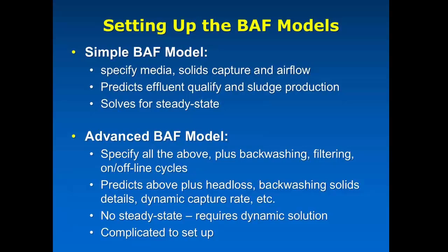It is quite complicated to set up. I'll be frankly honest, it's actually the most complicated thing that we have in GPS-X, is the advanced BAF model. And I had worked on a couple of projects recently where I didn't need all of that detail. I just wanted to get the right amount of surface area with the right amount of aeration and so on. And so we created the simple BAF model to be able to do that job. So if you're new to BAF modeling, I suggest sticking with the simple one to start.